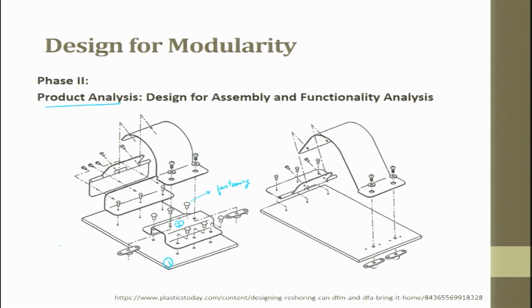So, it is supposed to lock some shaft or something like that. So, this is the previous component which was made. Once we use the concept of design for assembly, you can see how many parts have been reduced and how the design has become more foolproof.